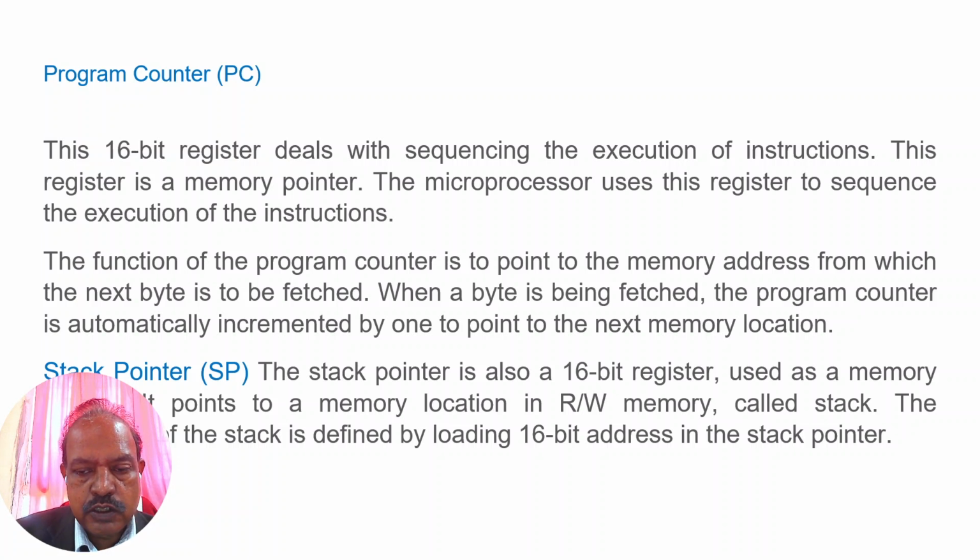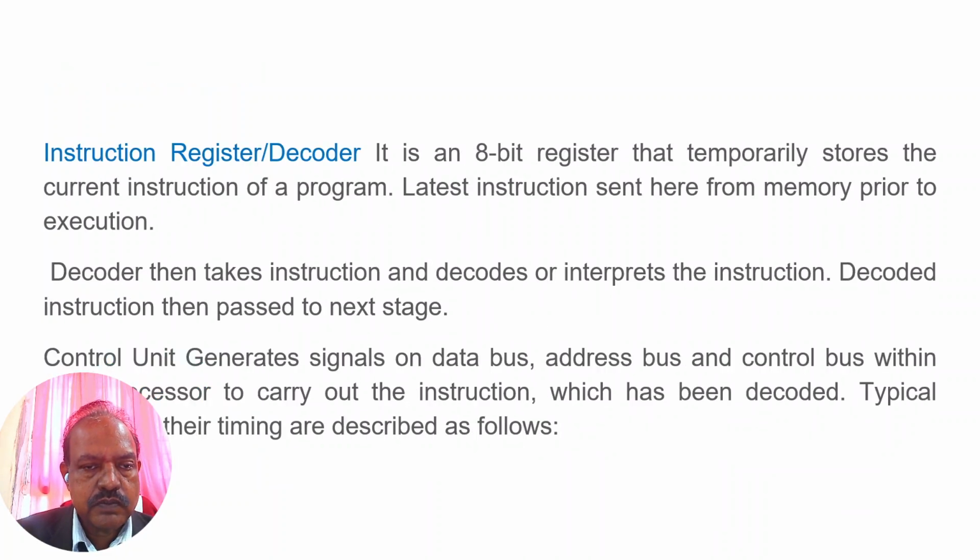Then the stack pointer. As you have seen, it is also a 16-bit register used as a memory pointer, and it points to memory locations in a memory called the stack. The beginning of the stack is defined by loading a 16-bit address into the stack pointer. Okay, you got some idea.